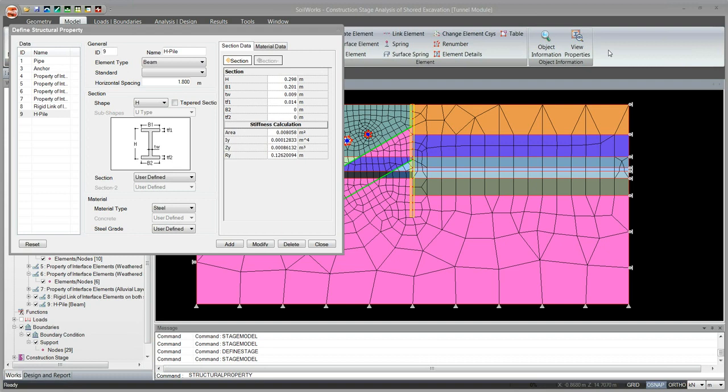Okay, perfect. And talking about the lagging again, since I said that it's a 2D model, the lagging will not be modeled. But this is the cross section at the location of a pile, and if you want to take into account the lagging, you can model a cross section where the pile is not present and then obtain the results for the same. But since it's not a 3D model, you cannot model the laggings. I hope I answered your question, Juraz, but we can talk more about it if you want.